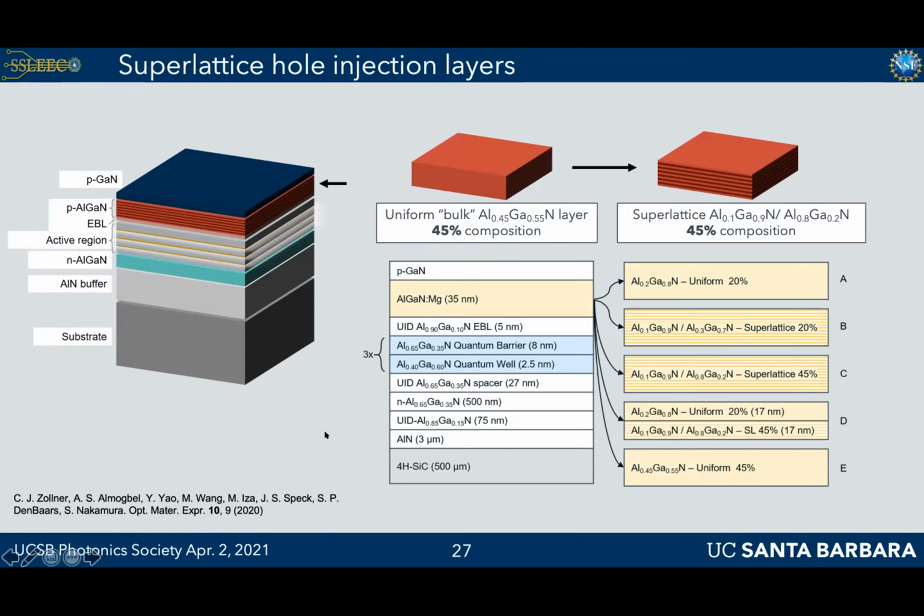Yeah, so that's something we definitely want to do. It's not something we've had a chance to try yet. There are a few results out there using tunnel junction. There are a handful of MBE results, and now there's also an MOCVD tunnel junction result. So it definitely seems doable. The voltages are usually pretty high, and you usually need a P-GaN or at least a GaN interlayer anyway.